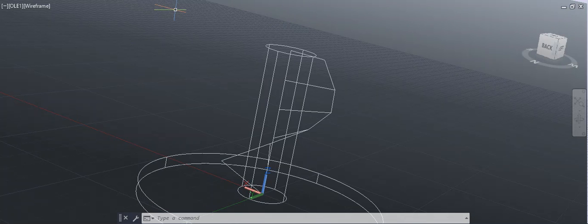And how do we convert this single line to a surface? I didn't know until I studied this particular wind turbine project myself. And I asked, how do I do a wind turbine? And I found a way. There's a command called surf network. Network. Everybody knows network, right? This is going to be the surf network command. So I type surf network.